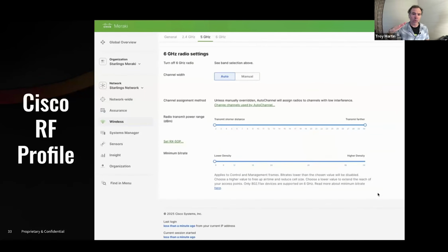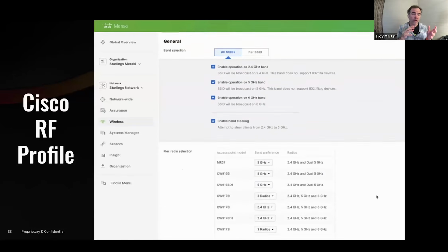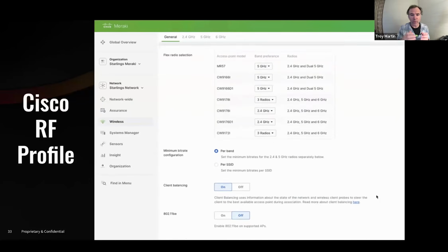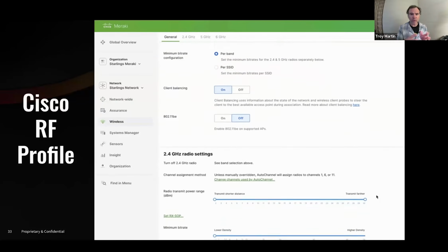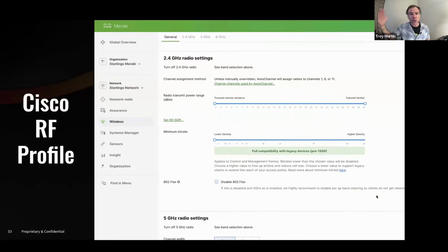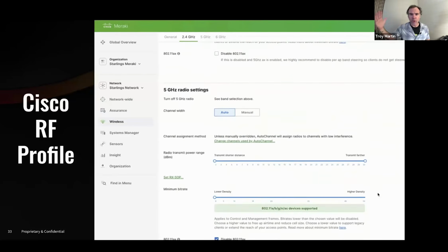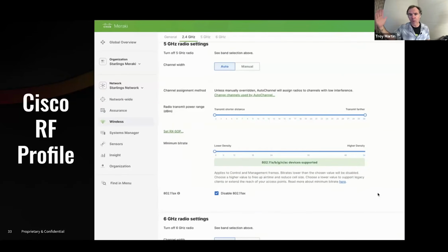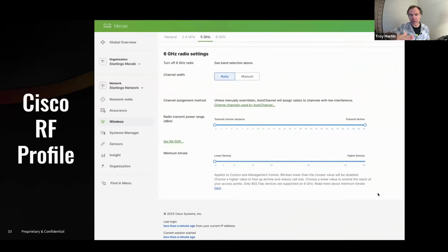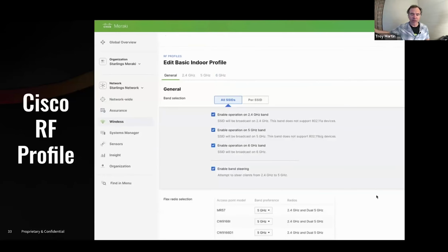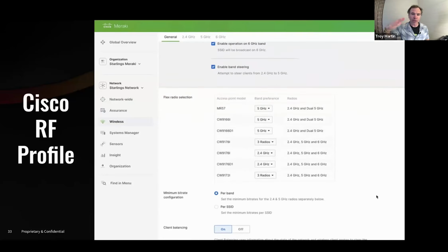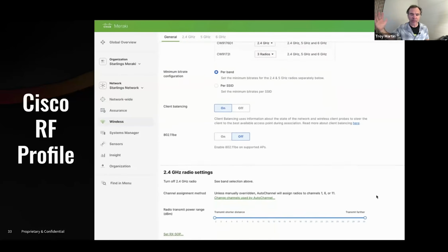And one of the really cool things that I like to do in Ekahau is, once you've built your model, and Matt kind of showed this earlier in the webinars, if you don't know the exact attenuation of the walls, you can model the what if scenarios. What if my walls were only 3 dB thick? What if they were 6 dB thick, right? Will my design hold up? And you kind of cover the extreme ends of that.